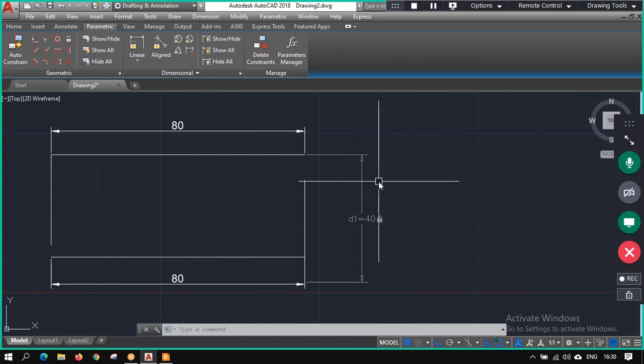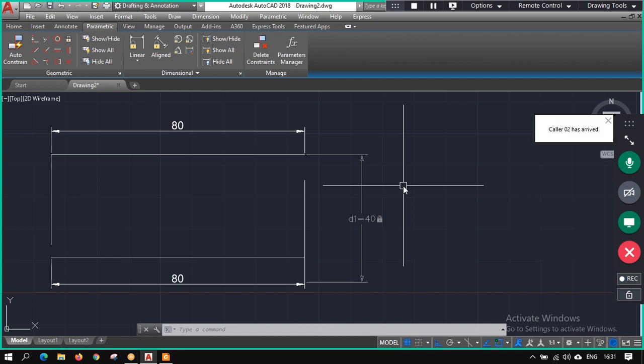So why I'm telling you this is that there are two types of dimensions. So you have to remember what type of dimensions you are considering. Now those who have used advanced software like SolidWorks or Onshape, they have directly incorporated this inside them. So you don't have to worry about it. You don't have to do anything. But it is also present in AutoCAD, but you have to know about it. It's not that AutoCAD doesn't have it. AutoCAD has it, but you have to find it out. In AutoCAD you will find this in parametric, but in other software it is given directly.